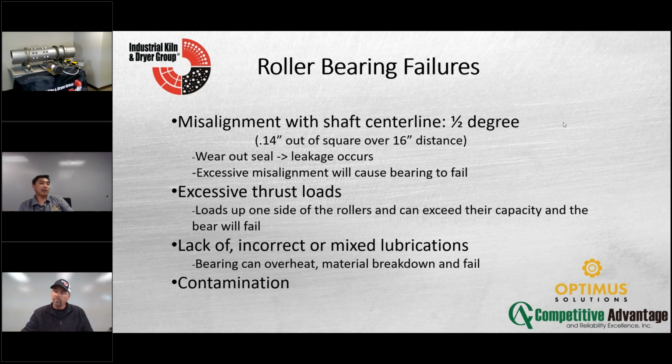It depends on the viscosity. It depends on if it's a kiln application or a spherical roller application. For kilns, you're looking at, say, a 400 centistoke viscosity range, depending on how hot it is, maybe on the discharge here, because it's hot.